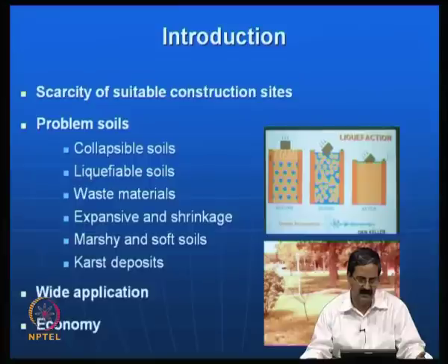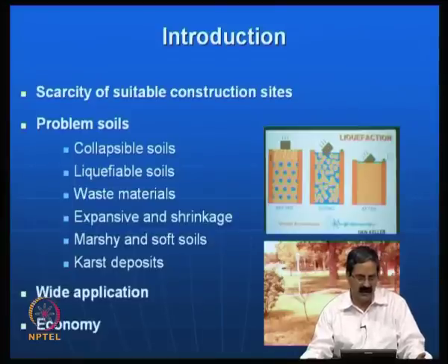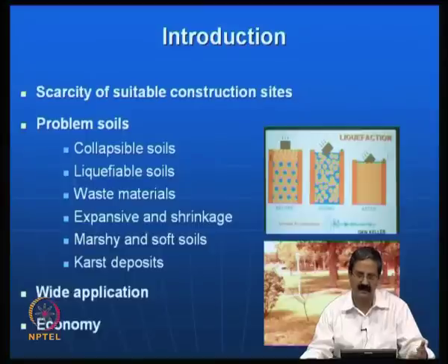Same is the case with waste materials like municipal solid waste or any other waste, because in soil mechanics it is possible to understand the consolidation behavior, for example in terms of primary consolidation and secondary consolidation and all that. But in waste materials you have a lot of biodegradable material, and it becomes very difficult to understand how these materials behave with time. This is a difficult challenge.